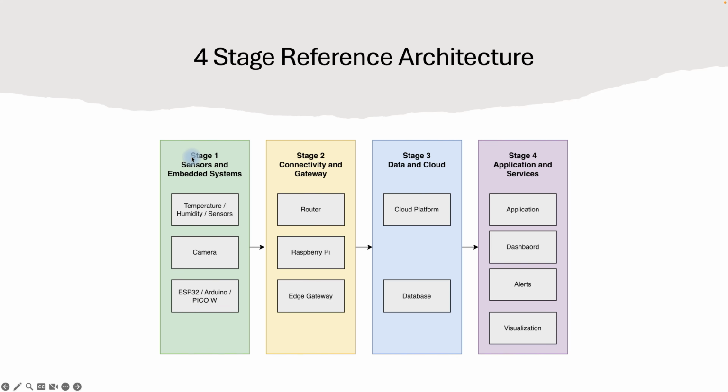And every sensor node is reading at least 5 different values. Now imagine 5 values on one node and there are 50 such machines installed. So there are at least 250 different sensor values being sensed in that one factory environment. Now, instead of sending all those 250 sensor values every second or every 5 seconds or every 10 seconds over to cloud, what is preferred is to keep an edge gateway, a local gateway which sits within the same environment,